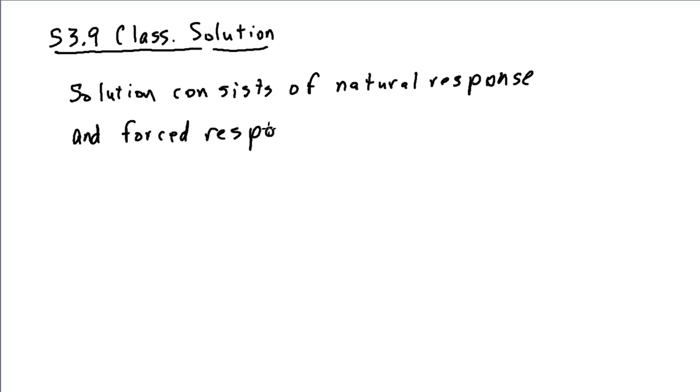These are slightly different than our zero input and zero state responses. Our zero state response will typically include some mode terms, the mode terms necessary so that all the initial conditions are actually zero. So the total solution is the same whether you work it out classically or via convolution.